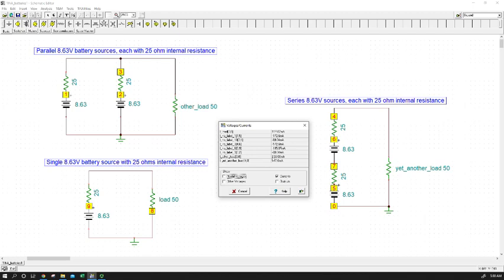Now, because we had two voltage sources, we were able to get 138.1, rounding off to one decimal place. We still couldn't get what we would have gotten with a single perfect voltage source, but we came closer. So that's a more noticeable and dramatic example of the benefit of putting multiple voltage sources in parallel. We haven't broken Ohm's law. We're still being limited by whatever the node voltage is up here, but what we're doing by running multiple sources in parallel is we're raising this node voltage that I'm kind of circling up here. And the higher this is, of course, we can apply Ohm's law, the more current will flow through our load resistor.